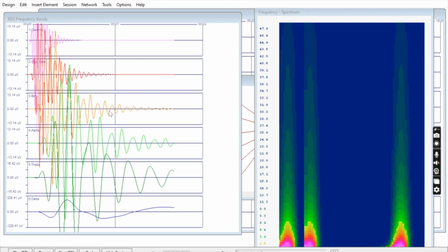The main thing to note here is that you need to tune these oscilloscope readings to display the wave in some way that's feasible. Obviously these are quite messy waves because everything's just spiking here, but within the reading that I was using this for, which was just for standard EEG for a meditation session, I've configured the voltage ranges here to display the waveforms how I want in this graph, and you can see that they'll come out of their graphs and overlap. If your graph's getting too messy, you can always click that group signal checkbox in the oscilloscope settings, as I showed before, and then it'll group all of these together and just show them in one.